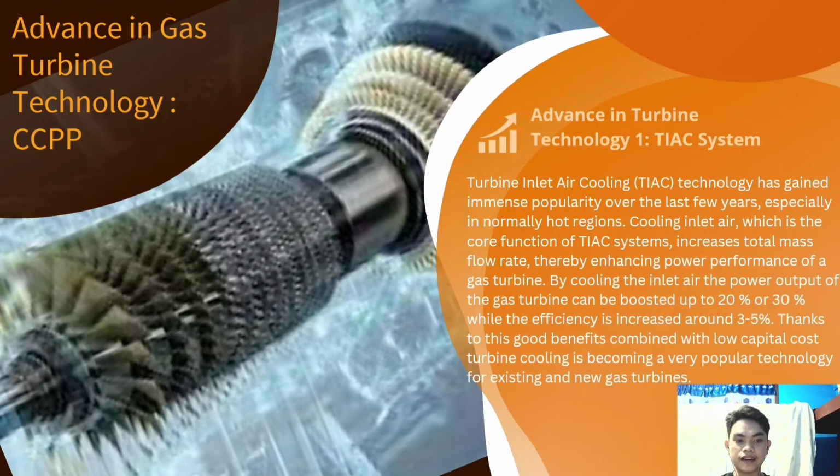Cooling the inlet air, which is the core function of TIAC systems, increases the total mass flow rate, thereby enhancing the power performance of a gas turbine. By cooling the inlet air, the power output of the gas turbine can be boosted by 20% to 30%, while the efficiency is increased by around 3 to 5%.